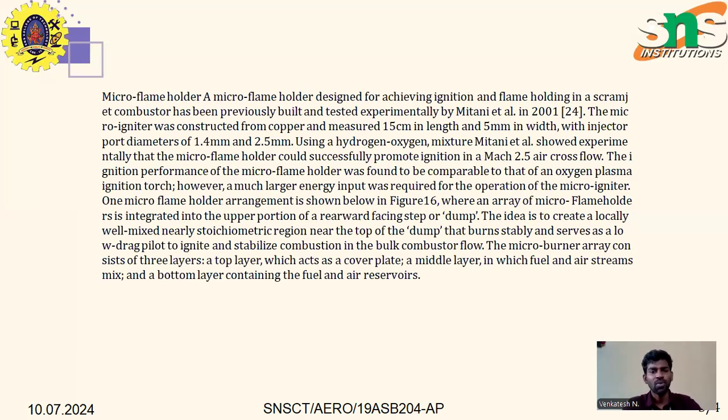A micro flame holder designed for achieving ignition and flame holding in a scramjet combustor has been previously built and tested experimentally by researchers in earlier research papers. The micro reactor igniter was constructed from copper and measured 15 centimeters in length and 5 mm in width, with injector port diameters of 1 mm and 2.5 mm.